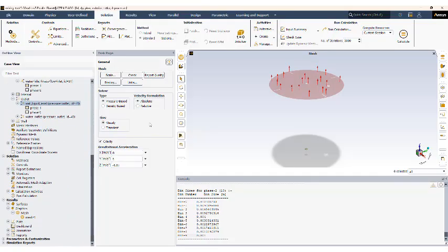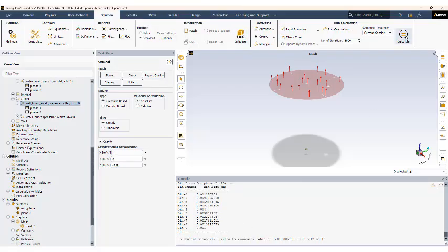So I should also mention that we are running a steady state simulation, and once we are done, we can actually do some post-processing looking at things like the contours for velocity and for diameter. So I created already some surfaces to do that. So I'll initialize the problem and then I'll run.